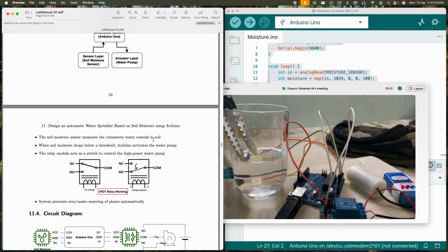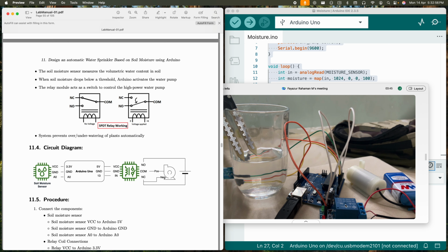So now how do we use the relay in the diagram? Like we said in the video, this is the relay. On one side of the relay, you can see this is our load, our pump, and then the external source that we are using. So this is the circuit for the pump. Now if you see the common terminal, normally in the default position, it is in the normally closed. You can see positive and negative are both not connected, so that's the reason the pump will be switched off in the normal position.